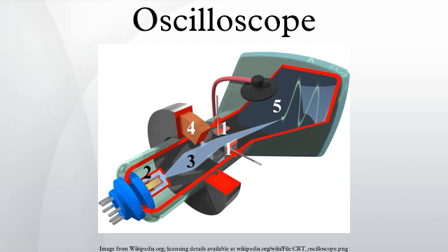For convenience, to see where 0 volts input currently shows on the screen, many oscilloscopes have a third switch position that disconnects the input and grounds it. Often, in this case, the user centers the trace with the vertical position control. Better oscilloscopes have a polarity selector. Normally, a positive input moves the trace upward, but this permits inverting, so a positive input deflects the trace downward.